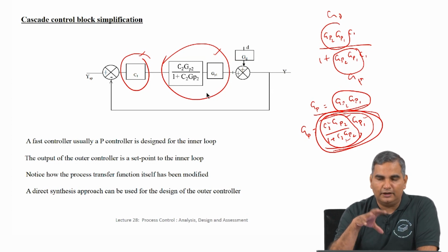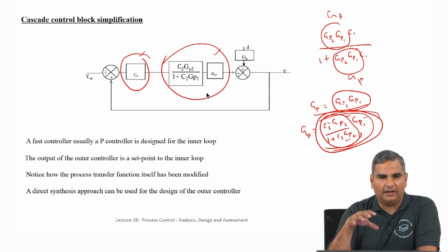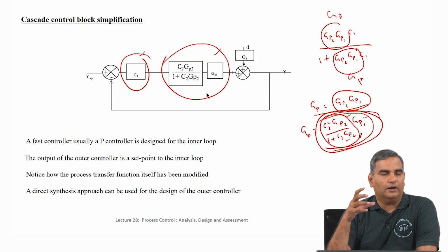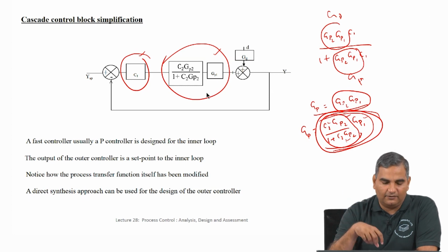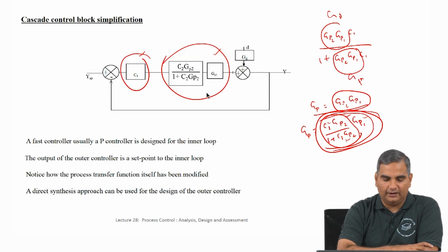Now if you really make it really fast, so that the minute I have a set point for stem position, I go there, clearly the dynamics is then only dictated by the stem to the flow, and that we are not doing anything about. We are only minimizing the effect of this valve dynamics by making that faster from a closed loop viewpoint in this case.